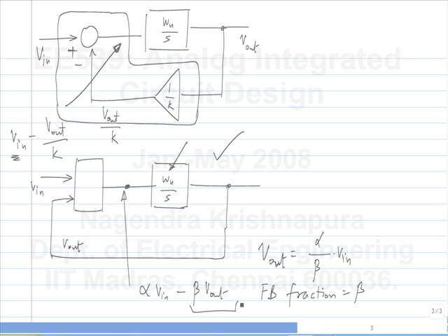Okay. So all I am trying to say is the gain doesn't have to be 1 over the feedback fraction. Is this clear? That's because the V in can also have some other factor other than 1. So in this case, the feedback factor is 1 over k and the gain is k. Okay. So this is the prototype negative feedback system, but in general the circuits you make will